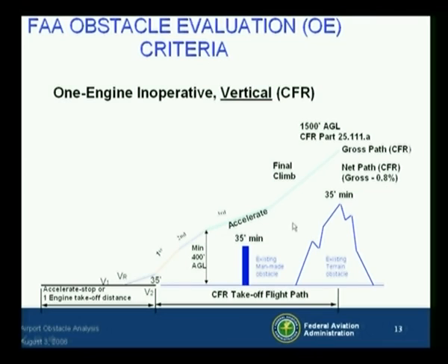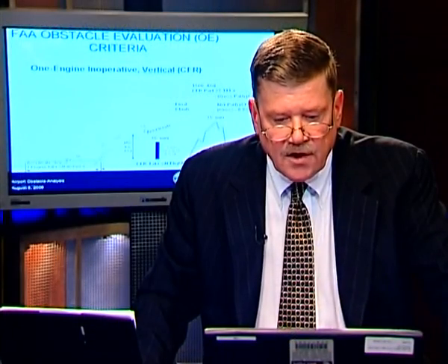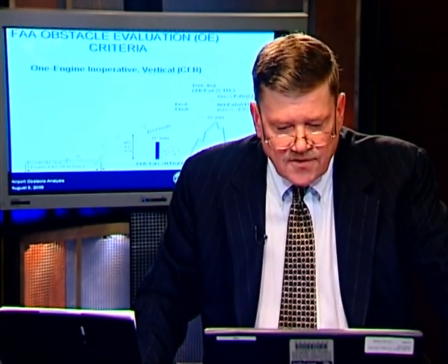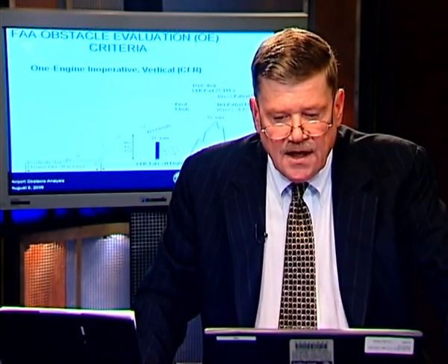process, and then get to the point where it can actually reduce to max continuous power. But you see in this example, that probably wouldn't be a good thing to do. The point is, between these 2 extremes of max power and V2 all the way to 1,500 feet, or cleaning up at max flap speed at 400 feet, is an infinite amount of climb profiles that the operator can choose to select. Most operators, as we know, go to about 1,000 feet and start on a normal profile and start the flap cleanup sequence. And after 1,000 feet, when there's VZF or flaps up speed, they'll select climb power and continue with the climb